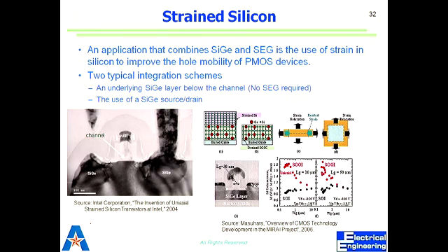Right? So strain heterostructures are simply made by epi, and what we get is many different types of materials. We can throw strained silicon on top of oxide. This is something which we see in a silicon transistor. The channel region is under strain, because they have different materials, silicon germanium on top of silicon, which results in stress at the interface.